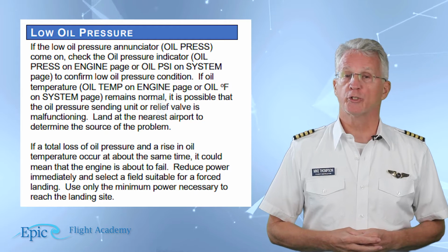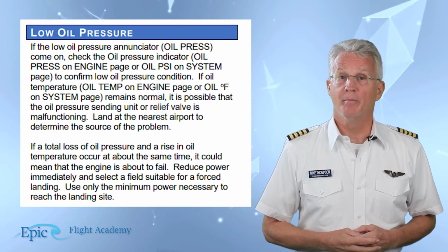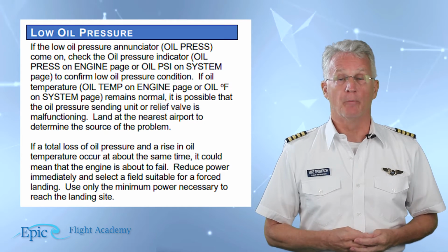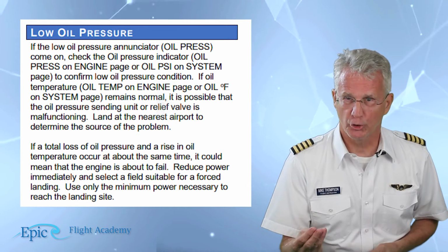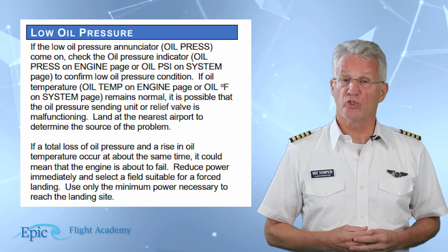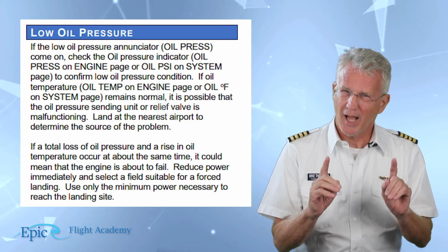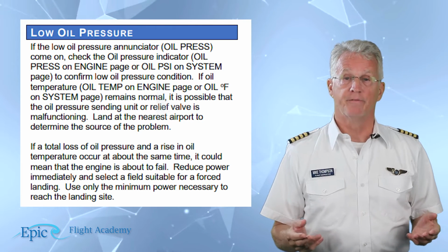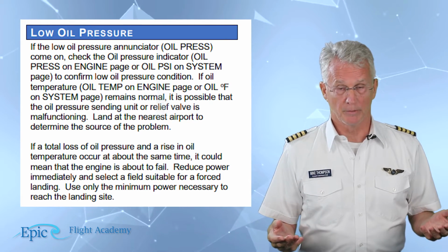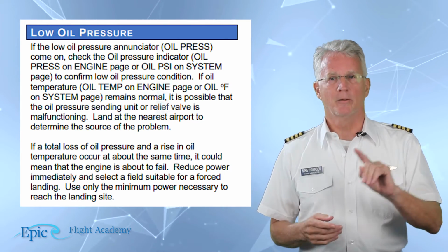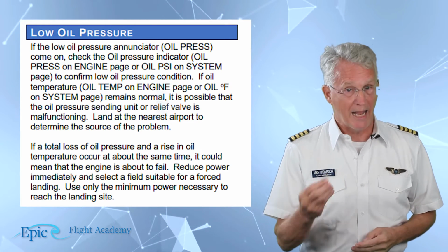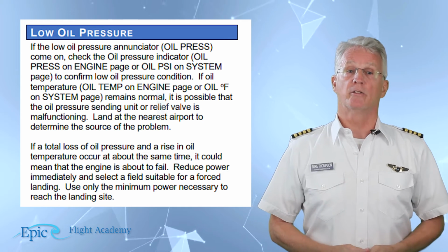Check the oil pressure indicator on the MFD to confirm the indication. Now, look at the oil temperature. If it remains normal, it is possible that the oil pressure sending unit or the relief valve is malfunctioning. But don't get complacent. Continue to monitor both oil temperature and pressure as the flight continues.